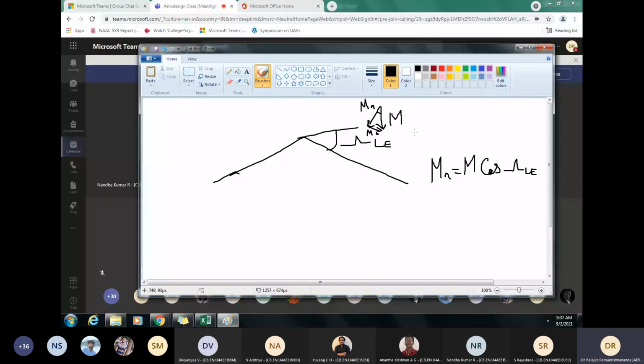So in case without the sweep, you have a straight wing, and you have an airfoil whose critical Mach number is 0.6. That is, if free stream M infinity is 0.6, then somewhere on the airfoil Mach number will be just equal to 1. Then it becomes less than 1 immediately, somewhere in the place. So that is 0.6.